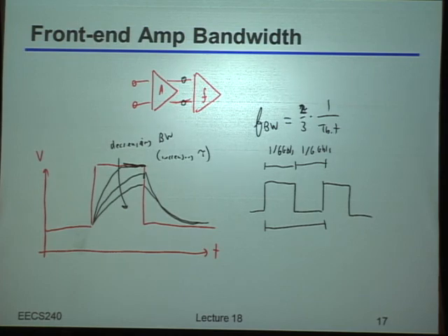Now, having said that, in this very specific example, where I assume that the channel was absolutely perfect, you will find, if you really did an optimization of what's the best gain versus bandwidth, you'll find that this 2/3 number is not the right answer. Okay, I'll tell you that now. It's actually going to be lower than that. However, you have to remember that there's always going to be extra amplification stages and poles in the rest of the system.